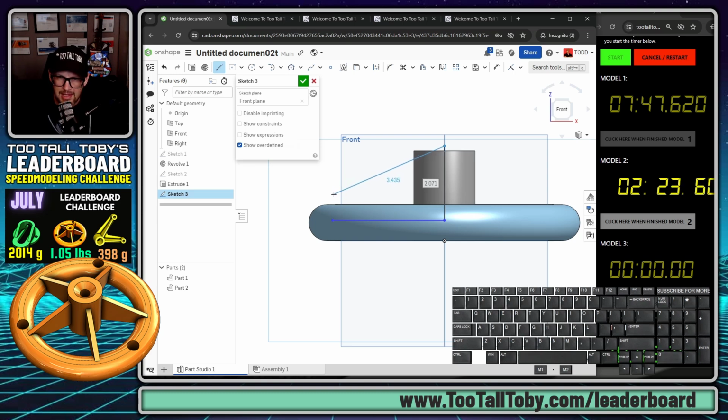Then coming back over to here, and then you're probably going to want to add a little bit of a flat spot just to avoid the model sticking out. But if the model is sticking out, we could use delete face, and we love using delete face in these challenges. So let's take a chance here. Let's see if the model does stick out a little bit. So this is going to go to 0.5 from the base. This is going to go at an angle of 25 degrees,